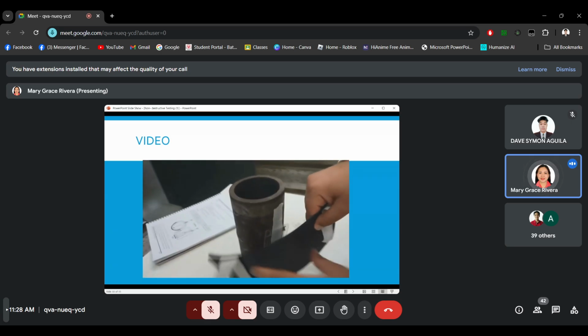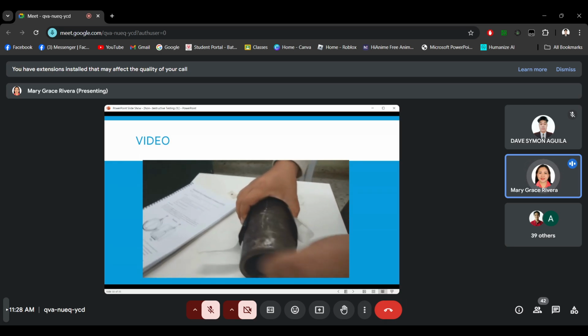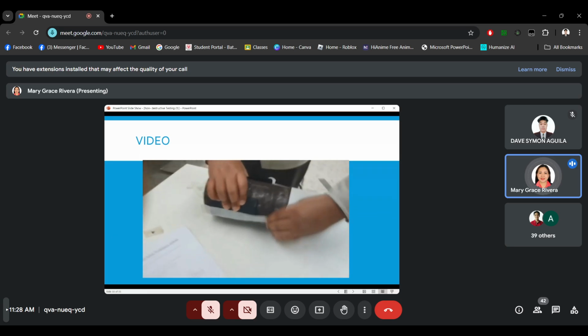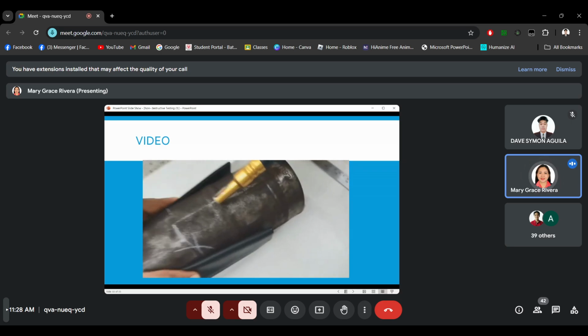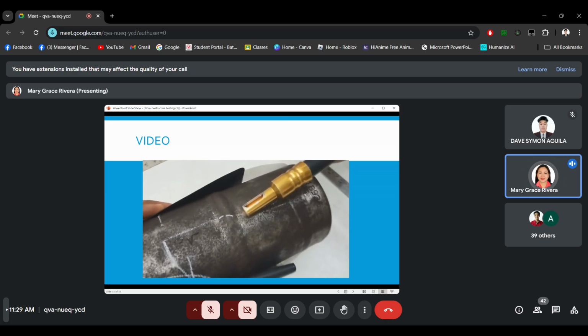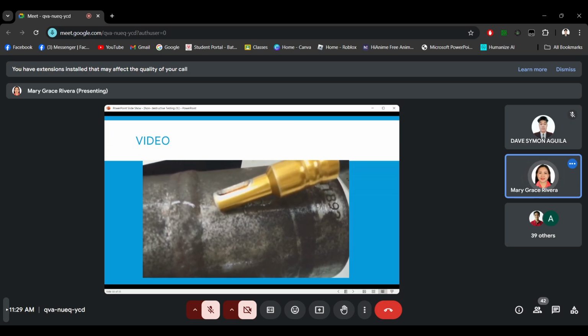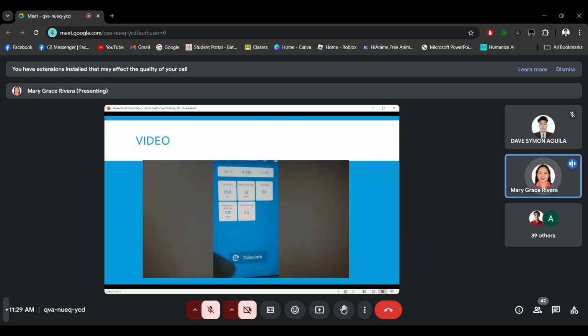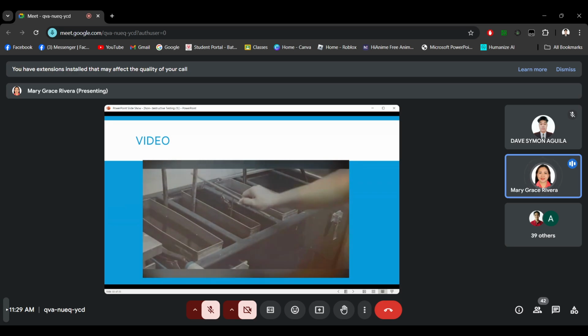Place letter F, which means film side. Because it is not like the other technique, which is source side, wrap the films around the welded pipe. Place the source at an angle of 10 degrees off the cap of the weld as you see, to take the film from inside. Calculate the exposure time by application. Process the films inside the dark room.